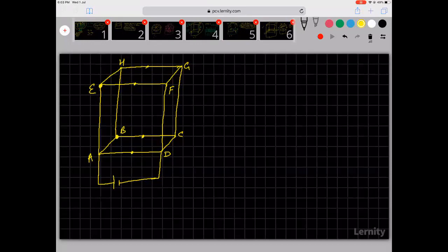How do you know? See, it is one resistor from positive. This is also one resistor from positive. Then it is two resistors from negative. Here also it is two resistors from negative. So E and B are at the same potential. But they are not at zero potential. If this is plus 5 and this is minus 5, they won't be zero potential. They'll be the same potential. Similarly, I can have points.